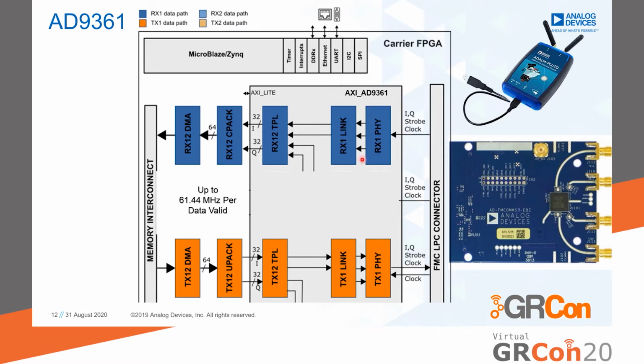And then that data is rearranged because it doesn't actually come in at 12 bits per clock as you might expect. It's a little bit different than that. So we actually reorganize that, and outside of this interface core here, we actually get samples that you would expect. So here we have 32-bit wide samples. So these are for dual channel I plus Q.